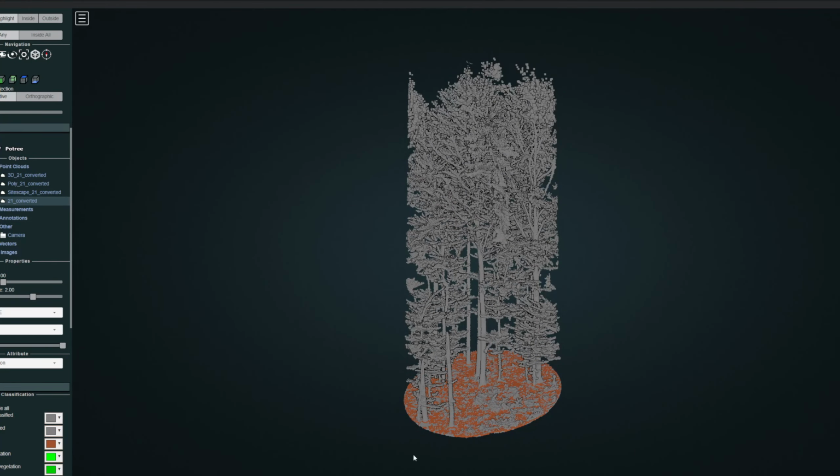This is where terrestrial LiDAR really comes in. It can capture a long distance. Mobile LiDAR, I believe, limits out around 15 meters. That may have changed with newer technology, but generally speaking, you're getting partway up the tree, but you're probably not reaching the tops. So that's one major difference between mobile and terrestrial.